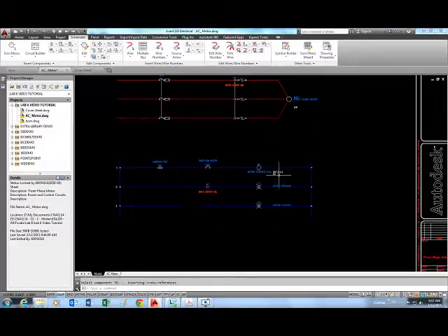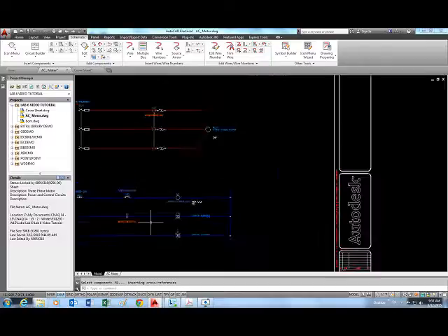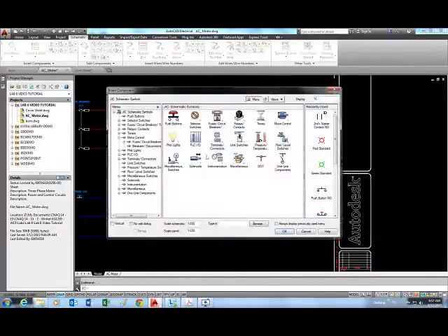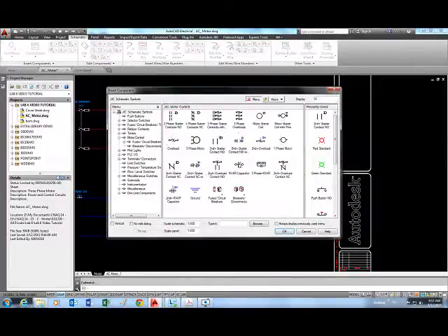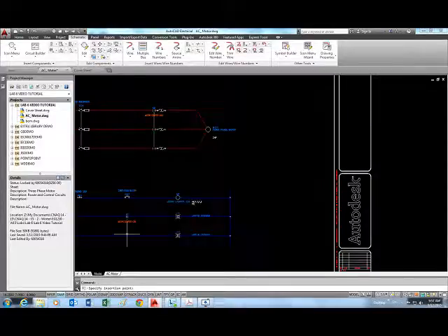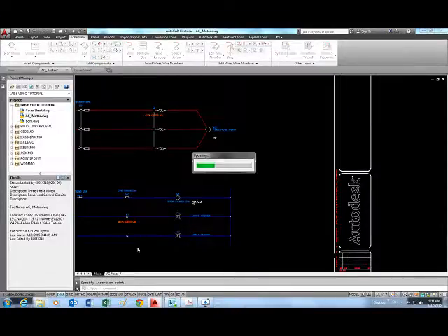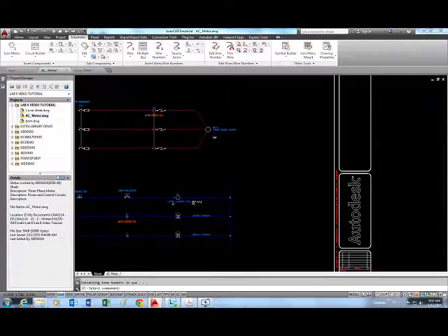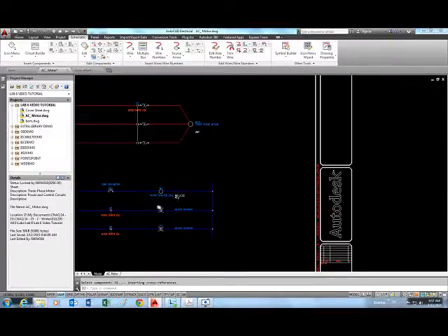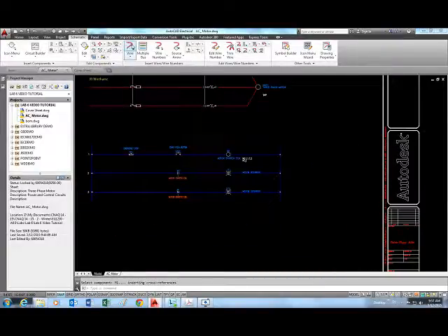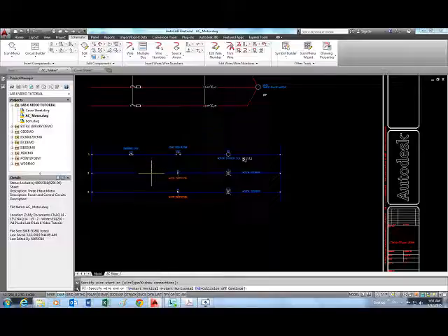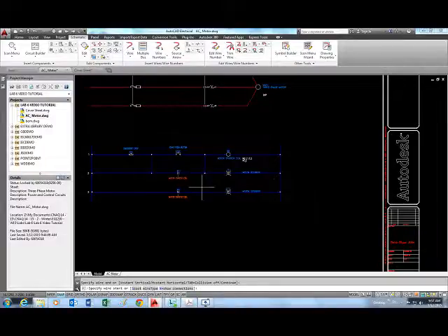We'll say OK. Now you can see also it says rank 2, there's another normally open contact, one more normally closed contact right here. Again, we'll go parent sibling with this to this coil, enter, and now you can see normally closed on the third rung. Okay, let's insert a wire from here to there, and then another wire from here to there, and trim this wire.